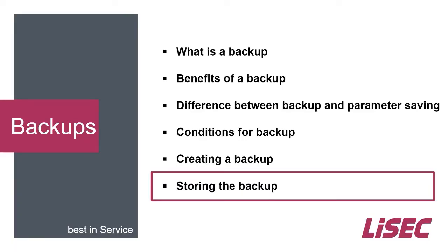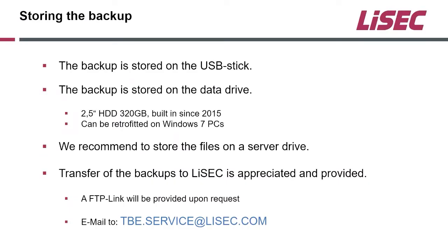The last one is how to store the backup. Because you need it when you have a breakdown. First, the backup is stored on the provided USB stick. So we provide the USB stick for the backup and we provide a USB stick for the parameters. The USB stick for the backup is also bootable. So you can boot up and restore from the same stick, but it means that the actual backup must be on this stick, of course.